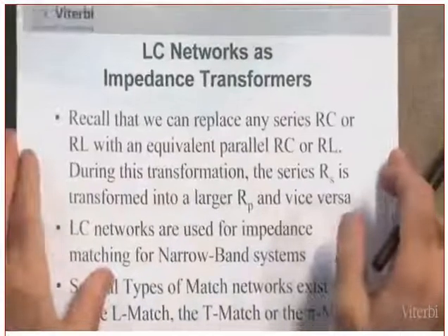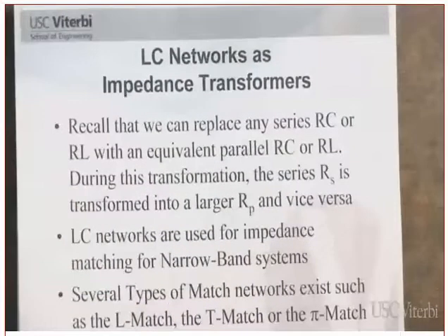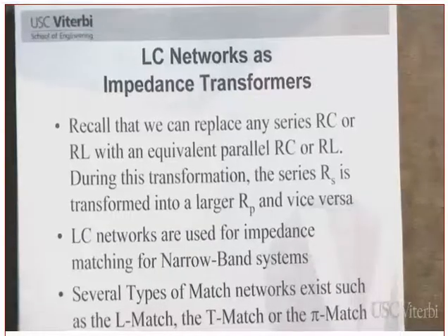We then studied the LC networks and LC type networks as impedance transformers, and we said that ideally, this is the most suitable type because it does not introduce any losses. So you can put the impedance matching network into the whole thing without introducing any additional losses. But this is, again, easier said than done.